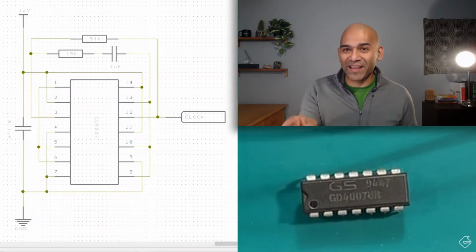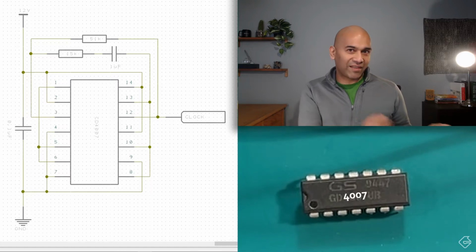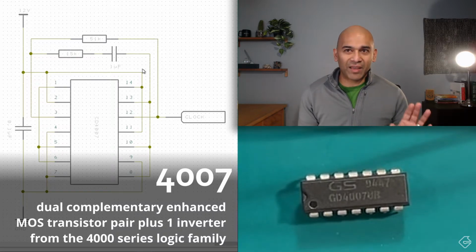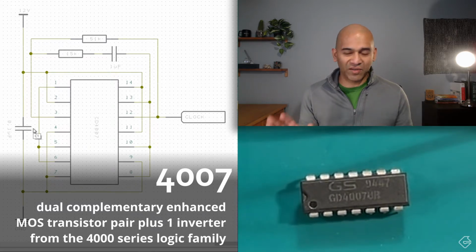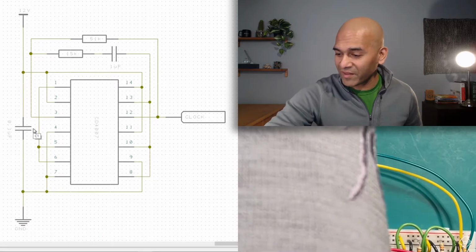Here's the schematic that I've come up with that will emulate the same circuit that I found online. So all it is basically, like you can see right here, there are 2 resistors that help with our timing and a 1 microfarad capacitor that's going to allow us to time that pulse. This other 0.1 microfarad capacitor just serves as a bypass capacitor. Anyways, the parts that we have are right here. So I've got everything we need.